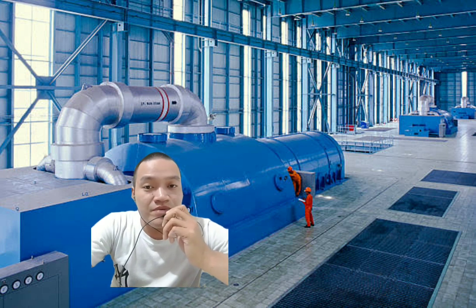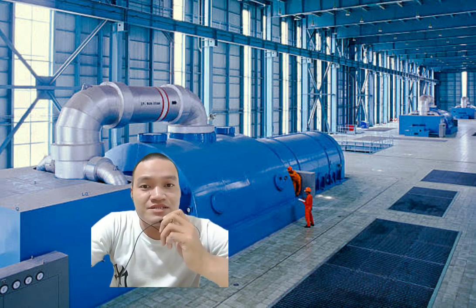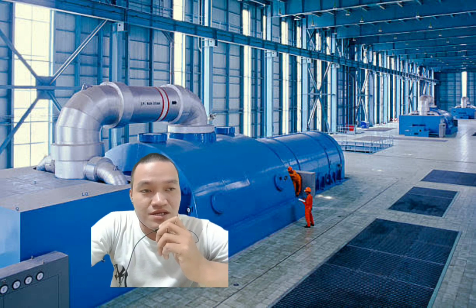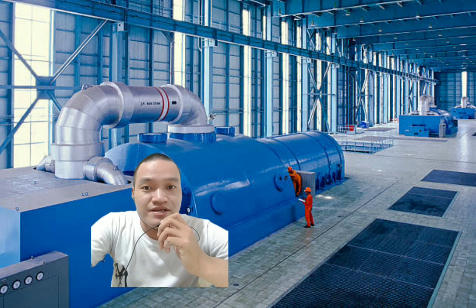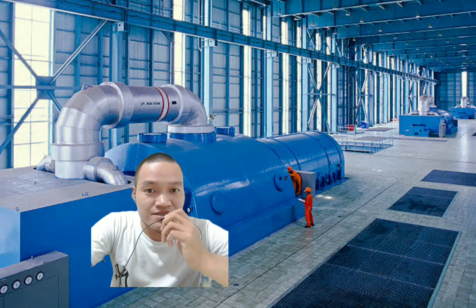First, open all the turbine casing and main steam line drain valves, and then ensure that all steam control valves at the maneuvering station and around the turbine blades are closed. Then all steam line drain valves should be open and start the lubricating oil pump. Check if the gravity tank is overflowing. Then obtain clearance from the bridge to turn the shaft. Engage the turning gear and rotate the turbines in each direction.